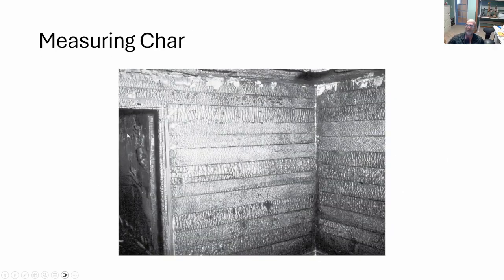So here's an example of a room. You can see the interesting blistering differences. Past forensic so-called experts have suggested that the differences in blistering may be accounted for by accelerants, and that's simply not the case. Here's a room from a fire test, homogeneous wall surfacing. It clearly shows differences that cannot be attributed to liquid accelerants. So blistering cannot be used as a tool or means of almost a binary pass-fail where accelerants were used or not.